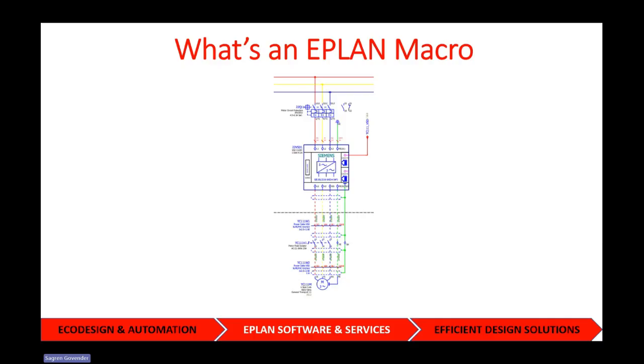What is a macro? So most of you would have heard of an Eplan macro. So what is an Eplan macro? It's basically any typical drawing, any typical diagram can be created into a macro. And this could be as simple as a symbol. You can take a symbol and create it into a macro. You can take a black box. So for example, you may have created a VSD using a black box. You can then create a macro out of that, save that macro, and then insert this into your parts database so that when you insert the device, the macro accompanies that device.